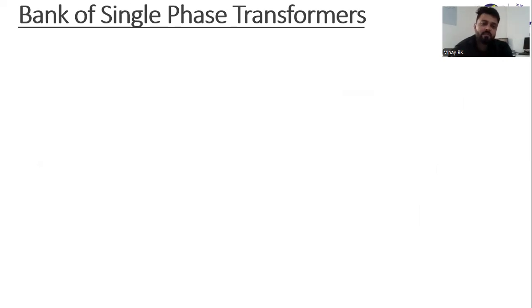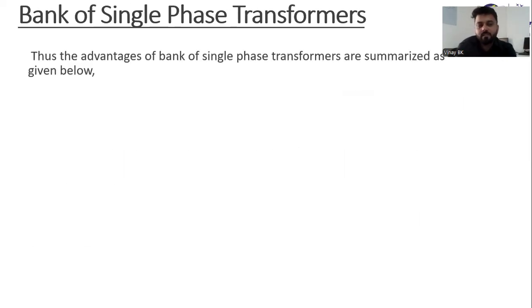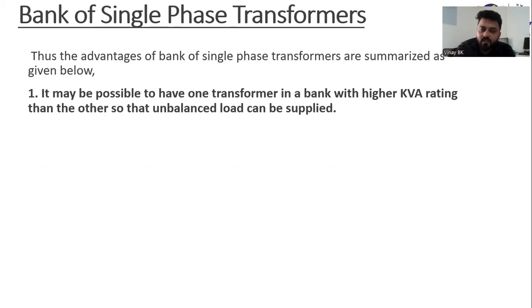Now, the bank of single-phase transformers. The advantages: if you have a bank of single-phase transformers, it may be possible to have one transformer in the bank with a higher kVA rating than the others, so that unbalanced load can be supplied.